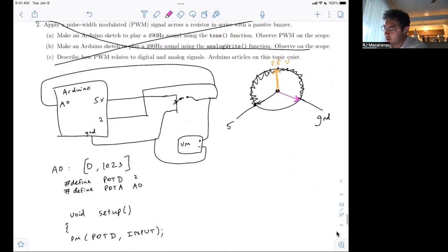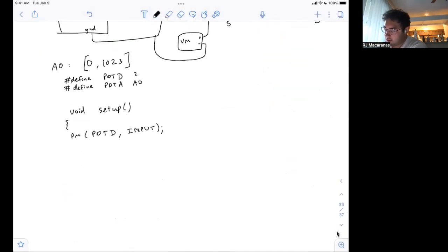If you look at the documentation on serial, you have to open with Serial.begin, and you just specify the rate at which we're talking so that the Arduino and the computer can understand each other. The serial monitor is this connection between the computer and the Arduino. They're talking to each other. So we have our Serial.begin, we have our pin mode set up here.